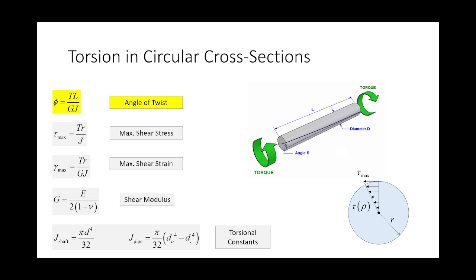Now, what are section properties? Section properties are just fancy numbers that characterize a given shape. For instance, what are some numbers that I could use to characterize this rectangular cross-section? The area, that's a section property. The perimeter, that's a section property. The centroid, that's a section property. Those are just numbers that characterize this shape, and that's all a section property is. I propose that J is just a different section property. It is a section property that arises from the derivation of the governing expressions for torsion. Now, here's something that I want you to recognize on the FE exam.